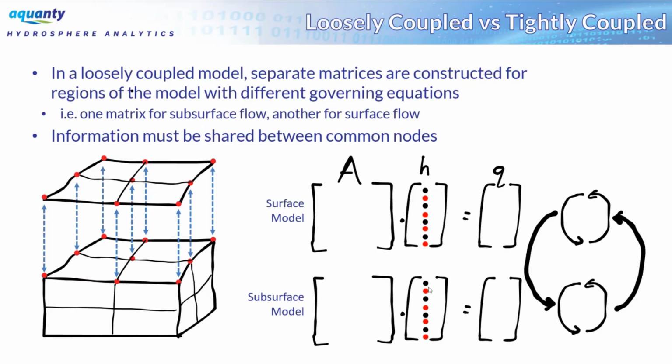The resulting head values are then mapped back up onto the surface model, and then back and forth, so you end up with a multi-layered iterative approach. First, the surface water model has to iterate potentially dozens or hundreds of times, solve, pass information down, iterate, and then back up, so the whole thing becomes two levels of iterations. So it's not extremely numerically sophisticated.